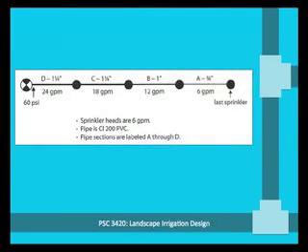Here we're trying to figure out what the dynamic pressure is at this last sprinkler on the lateral line. The information given includes the pipe sizes in between the sprinklers, so that's what these numbers are here. So 3/4 inch, 1 inch, 1 1/4 inch, 1 1/4 inch. And this, by the way, is typical where you will have different pipe sizes along a single lateral.